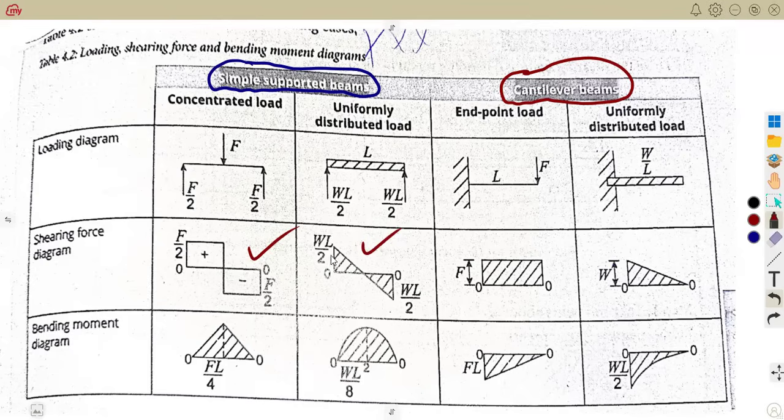You heard this in your N3. The only part that is now extended to you is this part of the bending moment diagram. For a concentrated load, your bending moment diagram is going to be going like this, okay? Take note where we have got this nature of a rectangle here. We are having a slanted line going up. When you are in the down region, you're having a slanted line going down. That is for the concentrated load. For the distributed, you'll be having a curve whenever you are having a force whereby you're going up in this nature, okay?